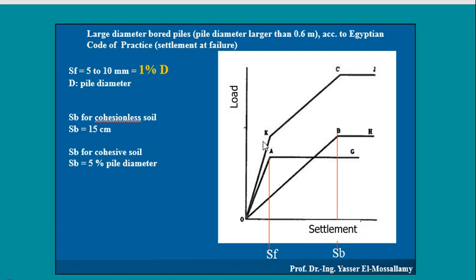How to get this? If you remember, we said that piles have two parts for loading, a part related to friction and a part related to end bearing. So the code will give me these two lines or these two curves. One of them represents the end bearing, and the other gives me the friction.